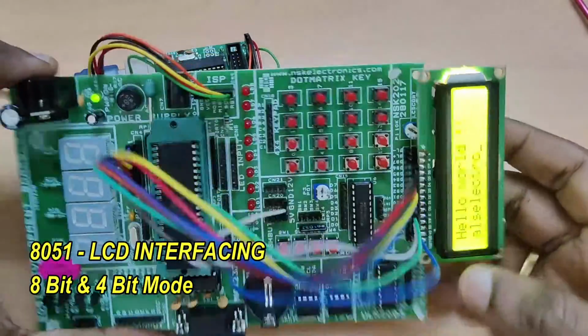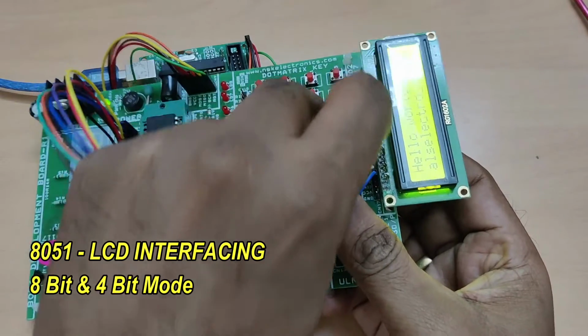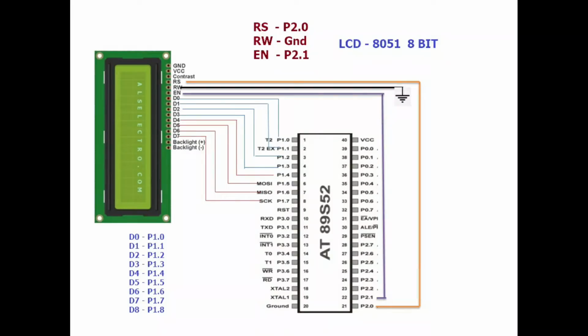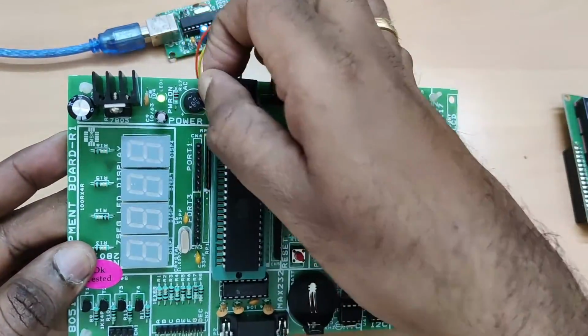Hello all. In this video we'll see how to interface LCD with 8051. We'll see both the 8-bit and 4-bit mode. First let's start with the 8-bit mode. Here the port register P1 is used for data bus, and two of the port pins of P2 is used